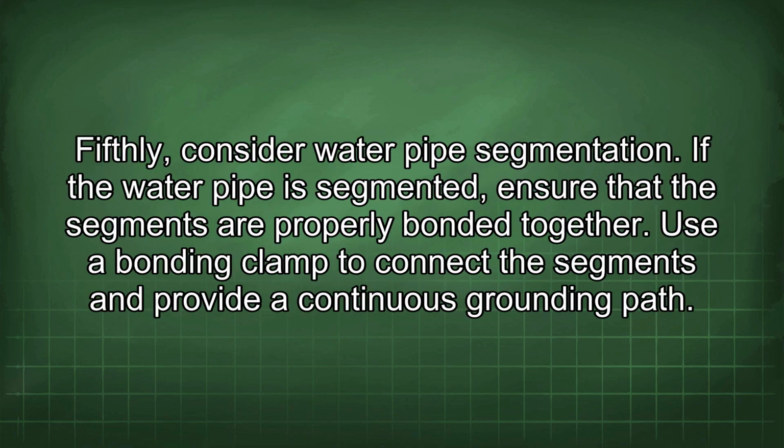Fifthly, consider water pipe segmentation. If the water pipe is segmented, ensure that the segments are properly bonded together. Use a bonding clamp to connect the segments and provide a continuous grounding path.